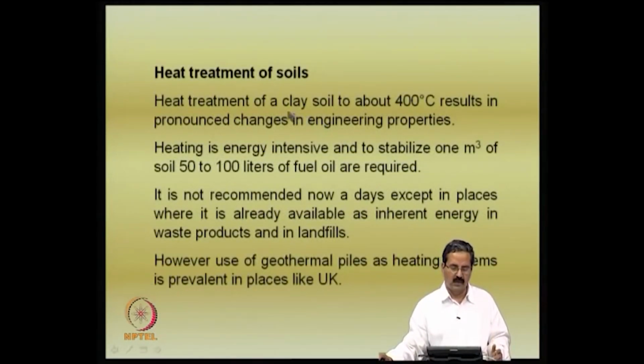How do you go about treating the soil? Actually this is a very important concept here. As I just mentioned, there could be even mineralogical changes that take place at higher temperatures. One should check it, particularly if, say, a halloysite mineral is present; there will definitely be significant changes in water content.